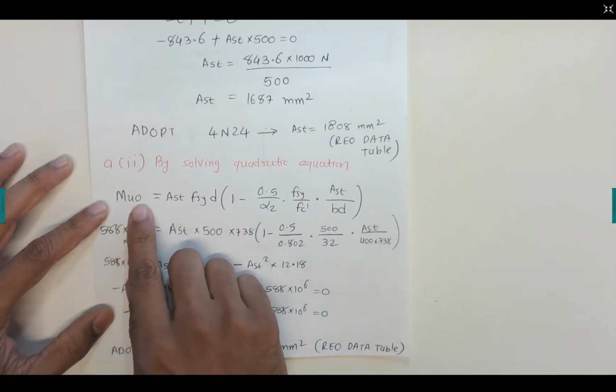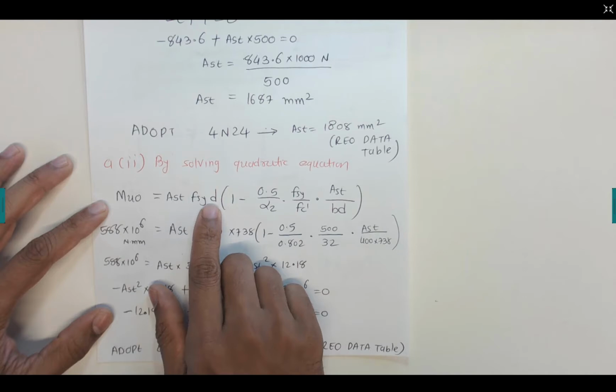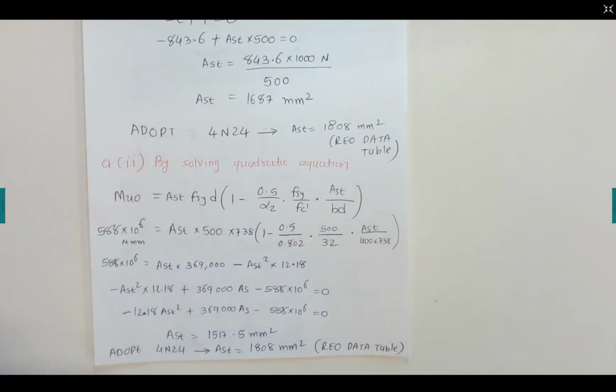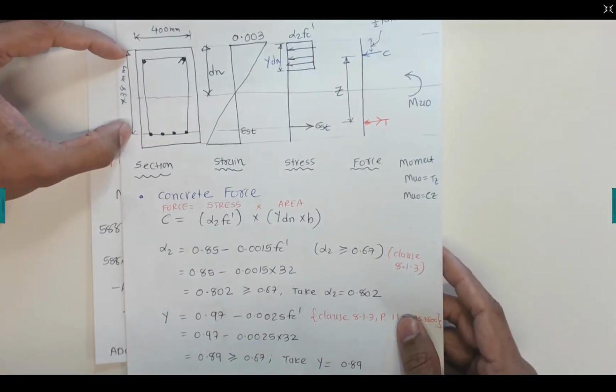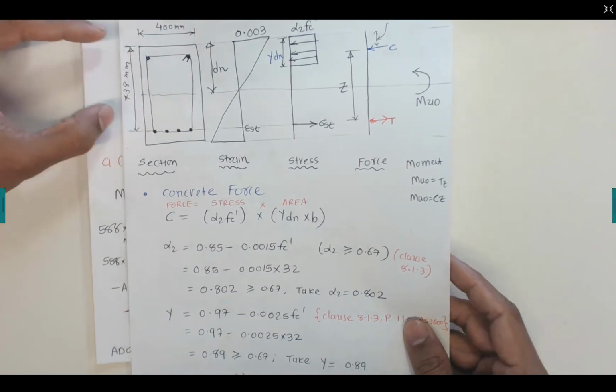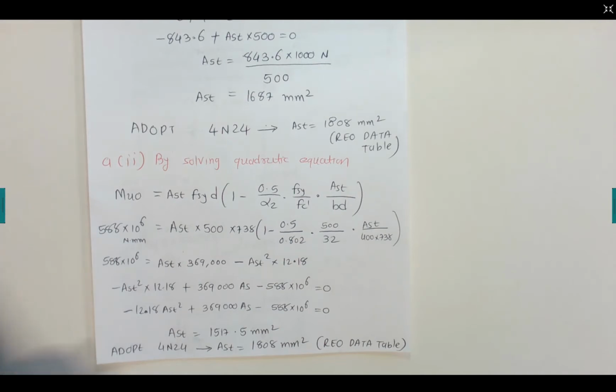calculating the bending capacity of the beam section. So that is Ast fsy d. Please note this d is not the overall depth. That d is not the whole capital D, but this is the small d that we just calculated, 738 millimeters in the previous video.